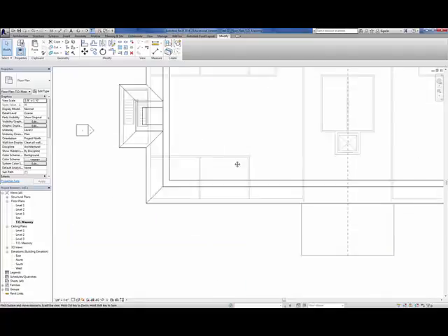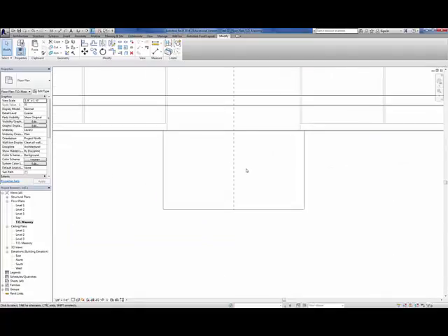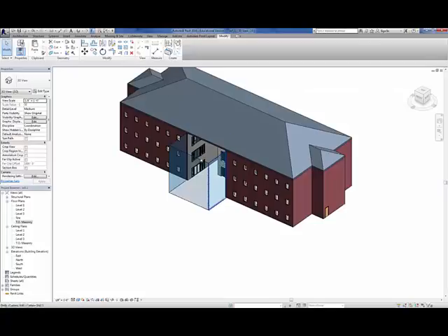And we're going to look at our atrium here. First thing we're going to have to do, if you look back in 3D view, is figure out some type of wall that's going to go across the top here, because these walls really should not be fitting in. This atrium is going to stick up just a little bit higher.